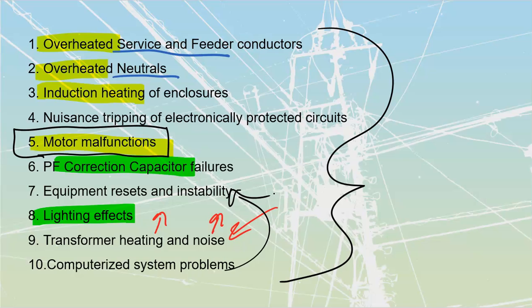Last of all, there's going to be mitigation. Mitigation really means stopping the problem, or stopping the process. Mitigation costs for power quality are going to be, first of all, all that time spent tracking down what the issue is, then changing anything, rewiring if you need to, improving your grounding and bonding, larger conductors, larger neutrals, changing out transformers. In some cases, you're just better off changing the transformer into one of those K-rated types of transformers, or installing power conditioning equipment, different types of filters and stuff like that we'll talk about later on.